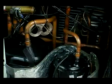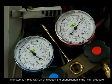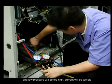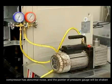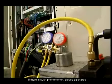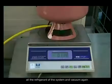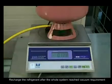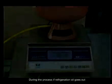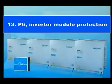If the system is mixed with air or nitrogen, the phenomenon is that high pressure and low pressure will be too high. Current will be too big, the compressor has abnormal noise, and the pointer of the pressure gauge will shake. If there is such a phenomenon, please discharge all the refrigerant of the system and vacuum again. Recharge the refrigerant after the whole system has reached the vacuum requirement. During the process, if refrigeration oil goes out, you should charge a suitable volume of refrigeration oil.